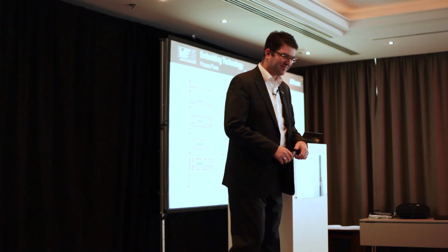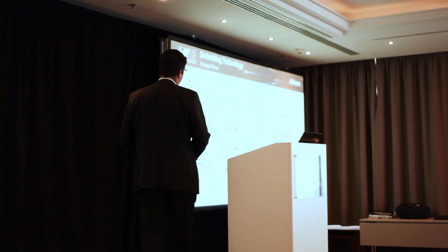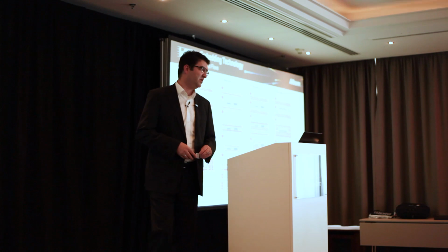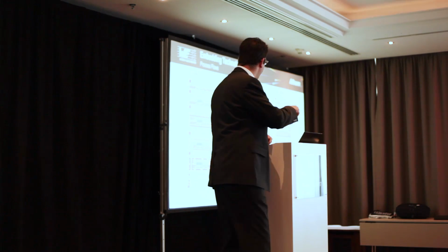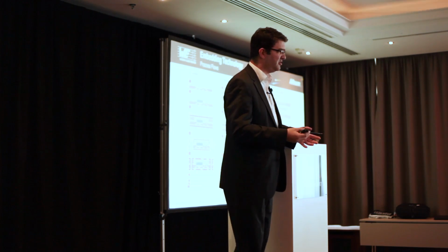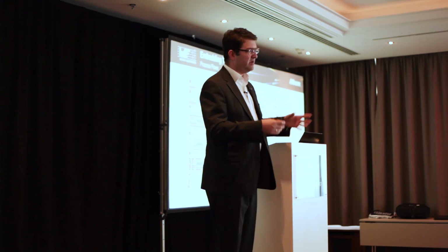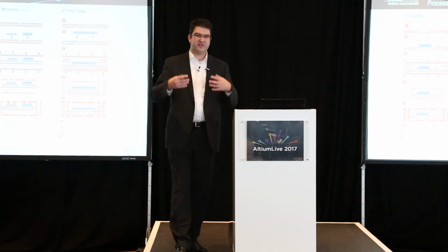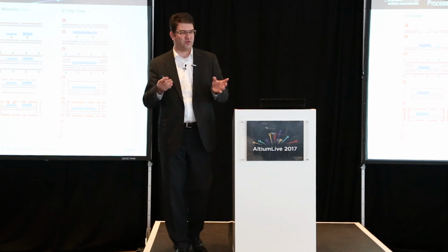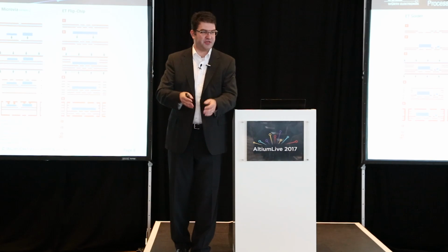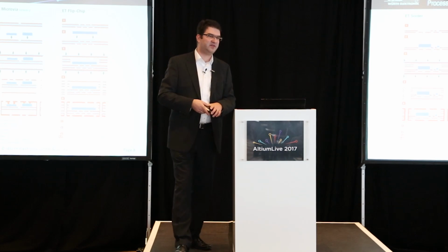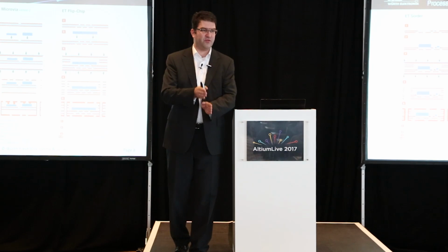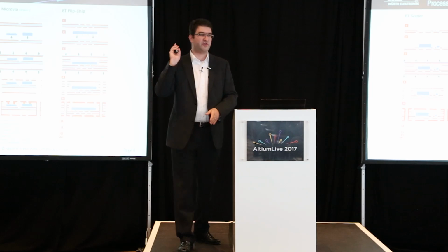Testing is actually done in different stages, depending on customer requirements and the application. We either test right after your assembly, but often it's not possible due to missing nets. Then you can test after the lamination, but still that might not be possible due to missing components. So it's always a discussion when to test what. Do you use an adapter? Do you use finger probe testing and so on? There are all different kinds of ways to deal with that. But you need to talk about it in an early phase, because testing here is rather critical.